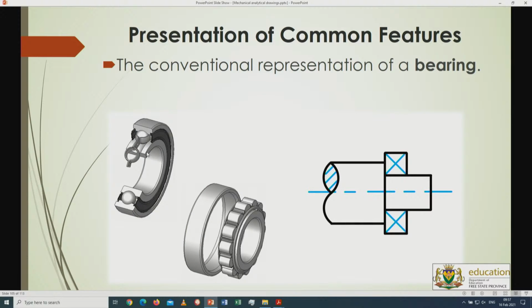Then over here, you can have a look at the bearing itself. This is what the bearing profile looks like. In other words, the bearing has been forced inside that area with, of course, a lot of grease and lubricant inside over here. And then we normally don't draw the detail of bearings like we have over here. We can just draw across through this part over here.